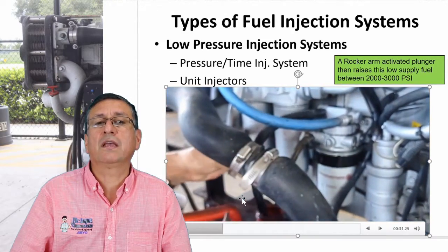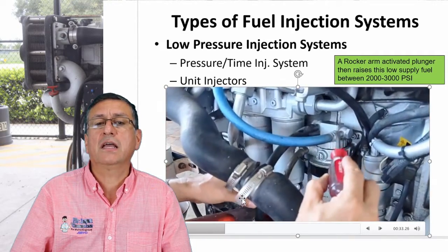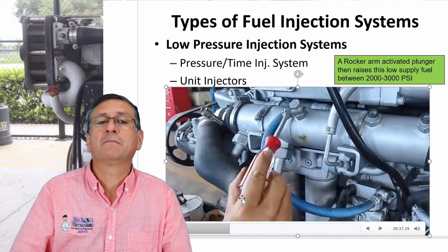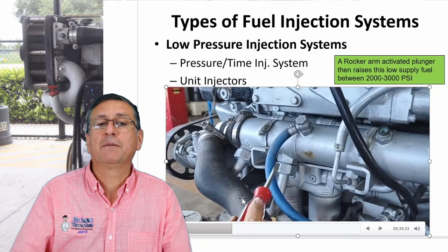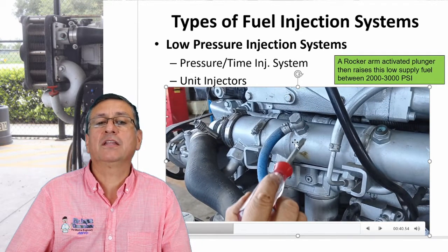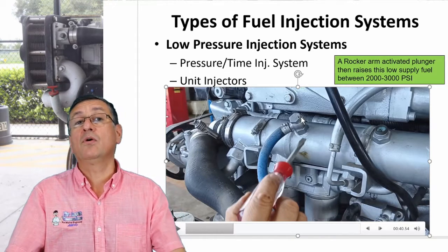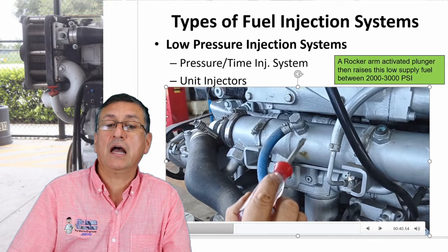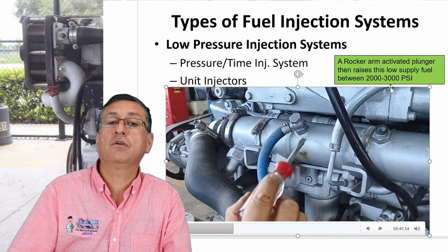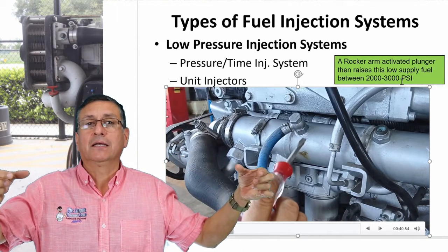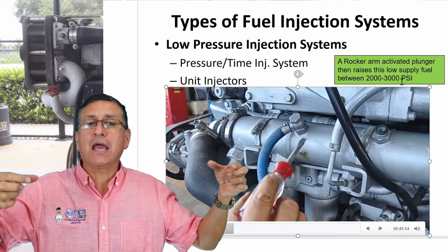The return of the fuel filter enters the tank, and the fuel with high pressure passes to the heat exchanger. Exactly. This is the compartment on the heat exchanger for fuel. This is the fuel cooler. Okay, and the fuel passes through an internal serpentine and continues here, and goes into the common rail in the head.